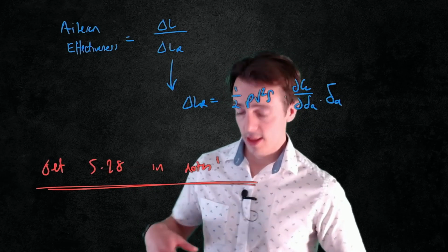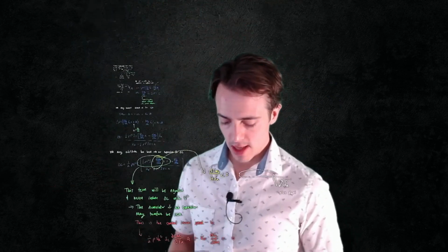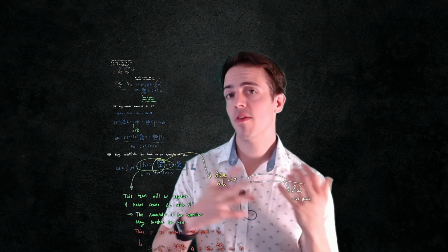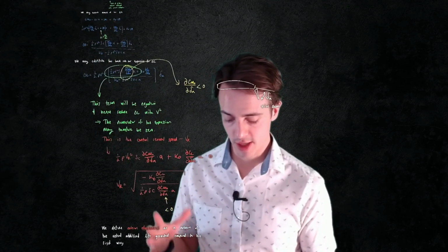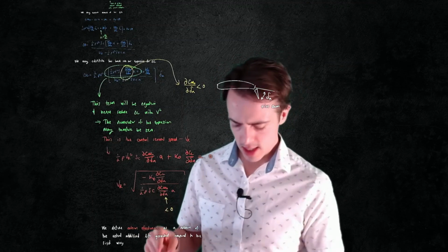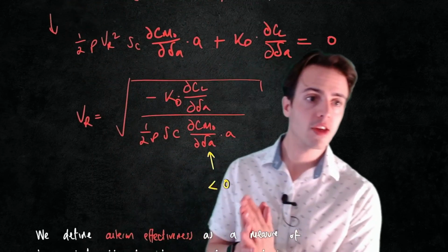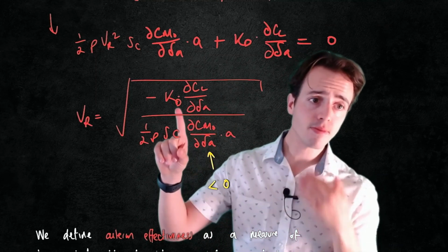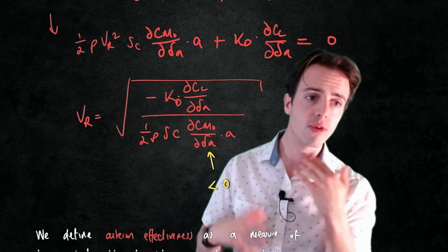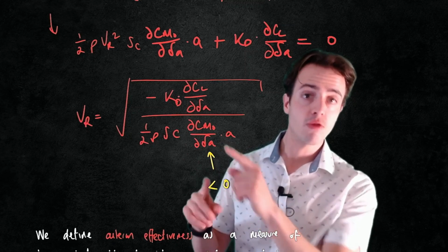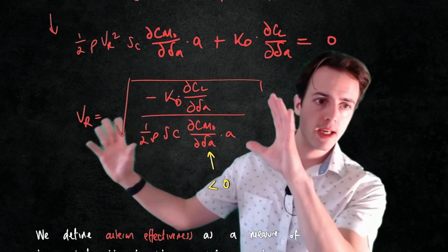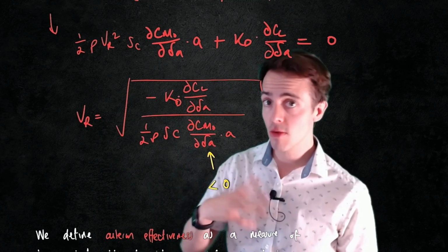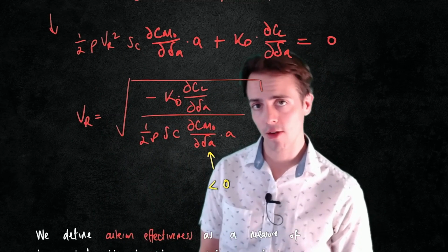Okay? That is a lot we've covered today. We went through the physical basis for control reversal, and we've now developed a model for it. So we've determined the control reversal speed, and we've shown that it is just this expression here. It's going to be a function of however much additional lift is generated multiplied by the torsional twist, and then however much additional moment is generated as well. Okay, so this whole expression here, we're going to be going through some problems next week that show us actually how we use these to develop solutions for real aircraft problems.